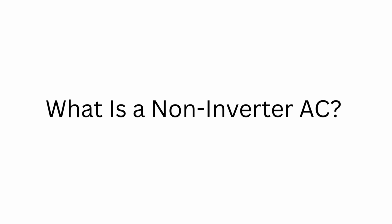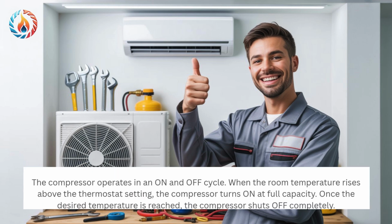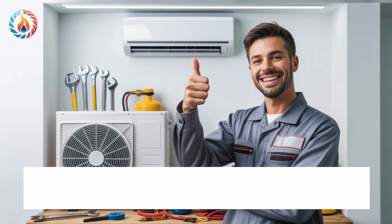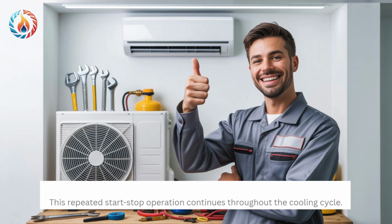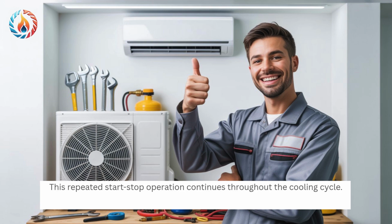What is a non-inverter AC? A non-inverter AC uses a fixed-speed compressor. The compressor operates in an on and off cycle. When the room temperature rises above the thermostat setting, the compressor turns on at full capacity. Once the desired temperature is reached, the compressor shuts off completely. As the room warms up again, the compressor restarts. This repeated start-stop operation continues throughout the cooling cycle.